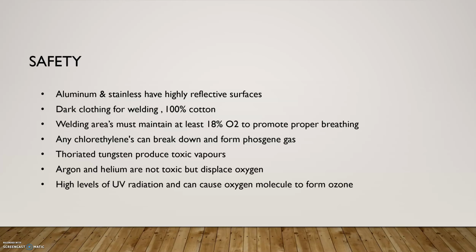A little bit of safety. Aluminum and stainless have highly reflective surfaces, so make sure to cover exposed skin, and darker clothing will reduce the reflection of light. Shielding gases are not toxic but can displace oxygen, especially in confined spaces.